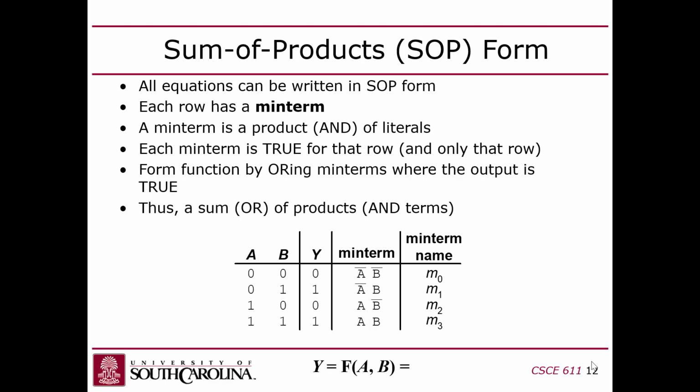Generally speaking, in the tools that we use, there's a synthesis phase I talked about last lecture that does iterative transformations to Boolean logic, right? So it has Boolean logic and it tries to minimize it by doing Boolean operations. It doesn't ever try to generate the whole truth table, right? Because that would grow too fast. You guys with me? But if you have the truth table, this is a way that you can go through it and construct a Boolean expression. You guys with me? Right?